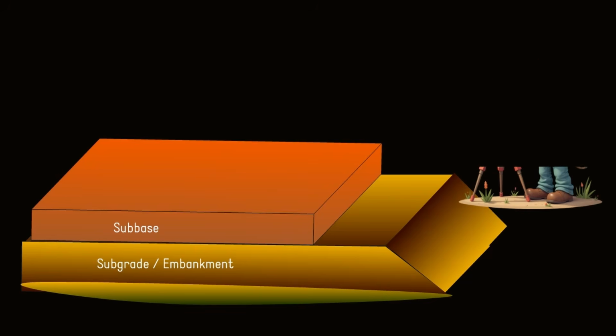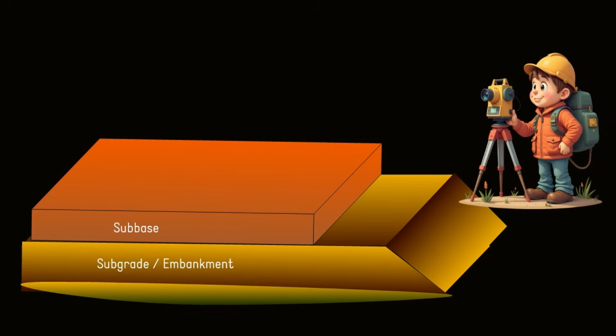Now, we will see the role of surveyors. This type of survey work is repeated in every stage of execution to control the width and thickness of all pavement layers, such as wet mix and asphalt works. Before the commencement of any work, the toe line shall be established by fixing pegs to mark the limits of the granular subbase. The pavement width for the toe line shall be calculated based on drawings, considering the formation width, offsets, slopes of different layers, and the depth of the current layer from the formation road level.